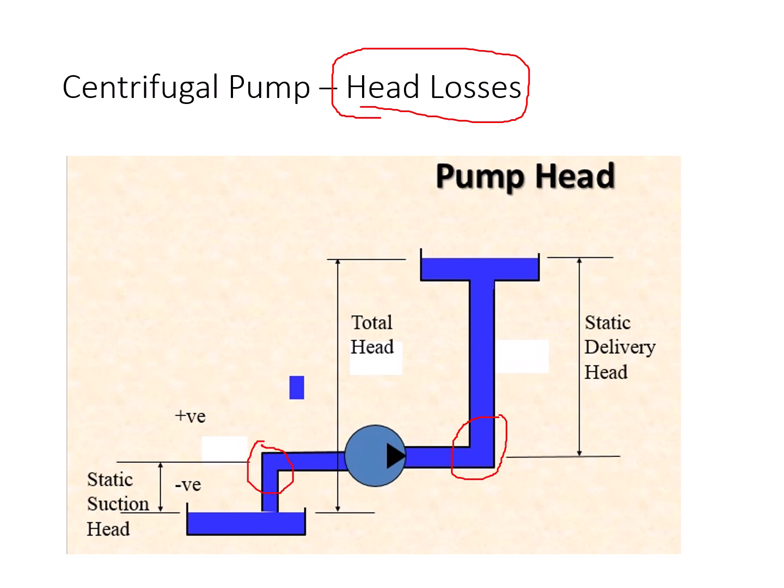So as much as possible, try to use fewer fittings. And most important, select a smooth pipe. Can go for PVC, plastic pipes as much as possible.